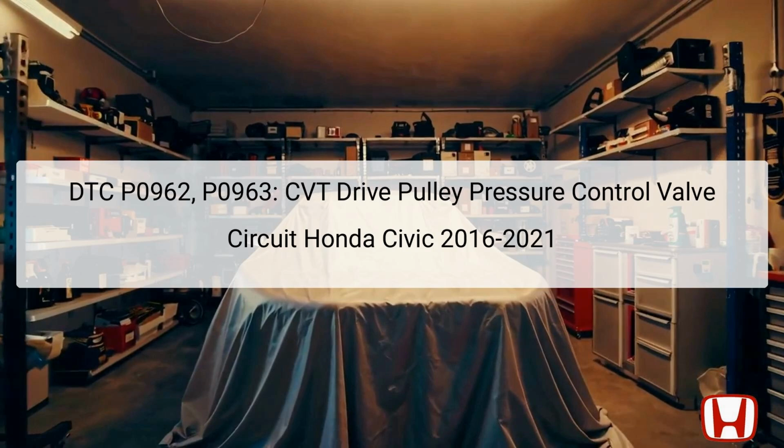DTC P0962 indicates that the CVT drive pulley pressure control valve circuit is low, whereas DTC P0963 indicates that it is high. The continuous variable transmission, CVT, plays a vital role in optimizing engine performance by seamlessly adjusting the gear ratio based on driving conditions, making these DTCs critical for maintaining optimal transmission operation.